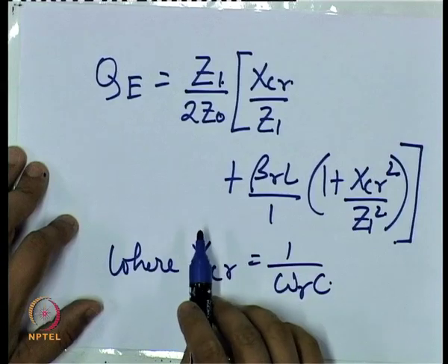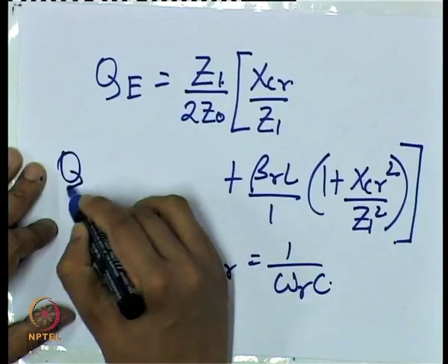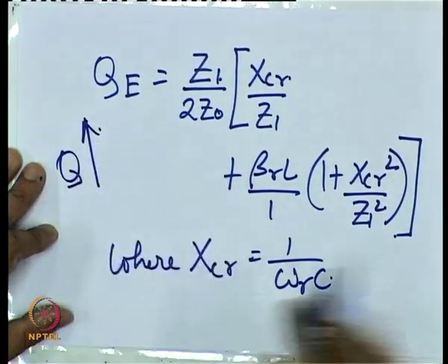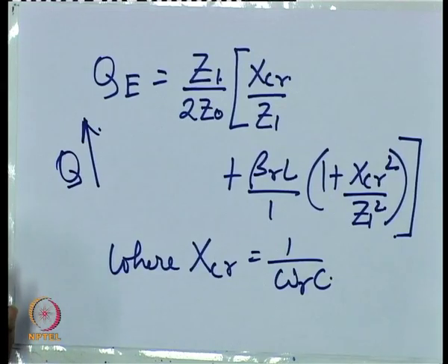The advantage of this is that we can get very high Qs. The Q factor that can be obtained is very high using this gap coupled resonator. So, in summary, we saw how resonators can be easily built using some standard microwave components like shorted lines or open stub lines, and how we can improve the Q factor of these lines using a gap. In the next module, we will see how using these resonators we can actually build the narrowband filters. Thank you.